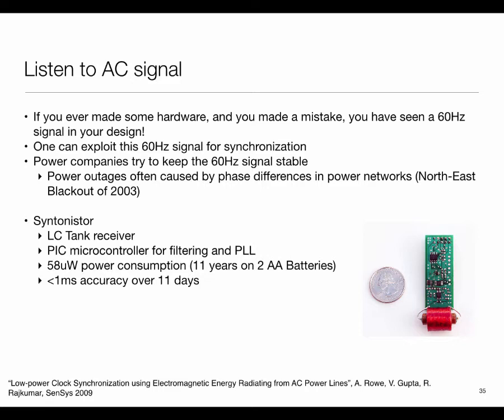In this country, it's 60 hertz, and it's kept very stable because it's kind of a universal agreement among all the generators who are hooking up to a grid, saying, hey, we all agree that we will remain at 60 hertz, and we'll strive to be at 60 hertz, because if the load increases, then there is a tendency for the load to pull down the frequency of the generator, and that translates into the rate at which the rotors of the turbines are rotating. So if the load increases, more mechanical energy has to be put in to keep it going. If generators start going out of sync, bad things happen, the blackouts happen basically.